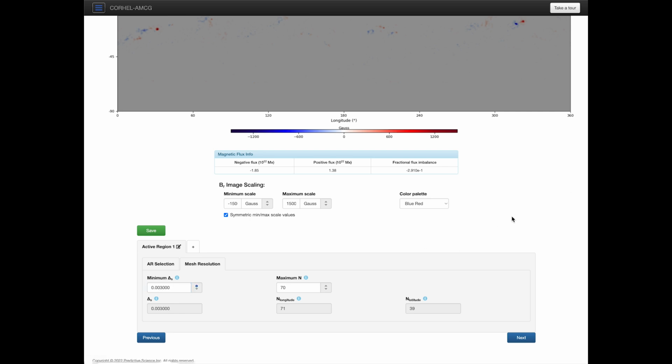Although the final resolution of the MHD calculations are set largely by your flux rope choices, entering a larger or smaller number here will control the smoothness of the active region into which you place the rope. As a rule of thumb, anything less than 70 points across will run reasonably fast in the interface. Next, one can optionally name the region to something memorable to facilitate interface navigation.